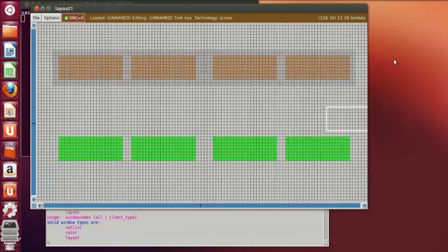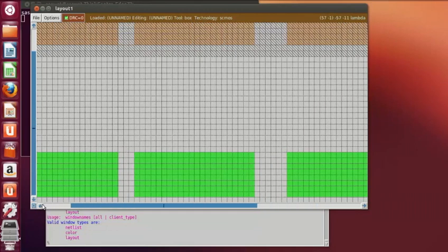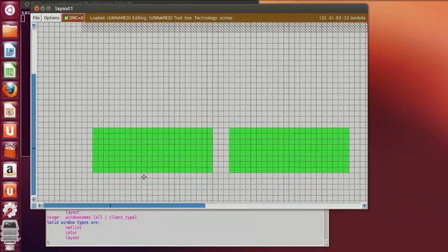for transmission gates. So in order to draw the inverters, first you have to draw the gate, that is the input. Zooming in helps us to find the width or draw according to the width. So this we have taken as 2 lambda. Okay, we can place over here.